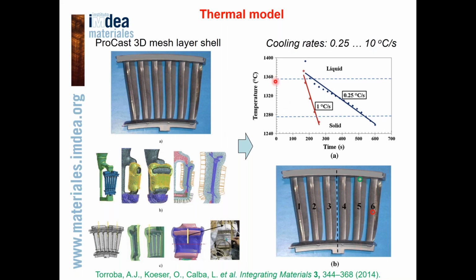So the theoretical results have shown that cooling rate during solidification and cooling process varies in a wide range from 0.25 degrees per second to 10 degrees per second. The lowest cooling rates correspond to the thickest parts of the nozzle guide vane, which are close to the gate, and the highest cooling rates correspond to the thinnest elements of the nozzle guide vane.